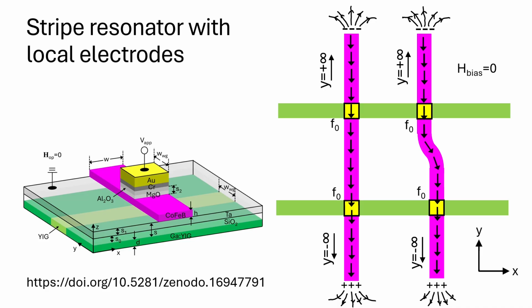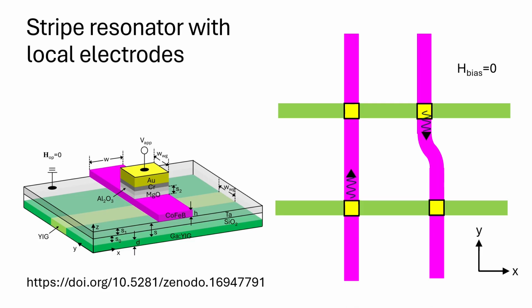This is very important from the perspective of circuitry design since signals are modulated into a single carrier frequency. If a resonator's resonance frequency is detuned away from this carrier frequency, it will no longer be able to function as a resonator. Okay, what about the aforementioned problem of spin waves traveling from one resonator to another resonator located on the same stripe? Isn't it that we don't want resonators to crosstalk with each other?